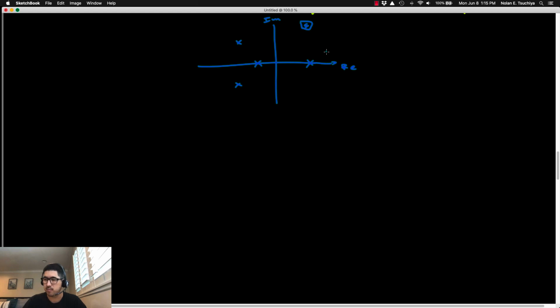You might be tempted to say, well, okay, fine, what if I add way more stable poles over here, right? Maybe I've got eight poles that are stable to try and somehow counteract that unstable pole. Is the system now stable? No, it's still unstable, right? A way to convince yourself of this is that no matter how many stable poles you add, if you have that one unstable pole, you're always going to be unstable.